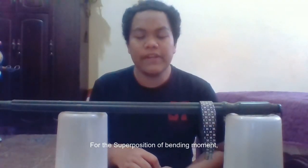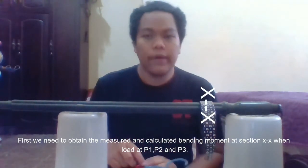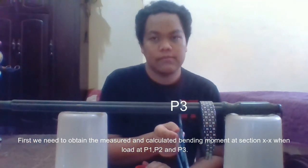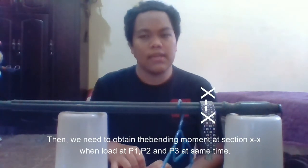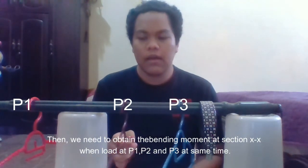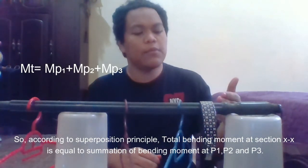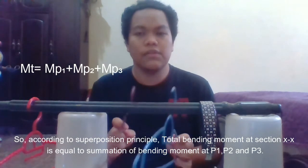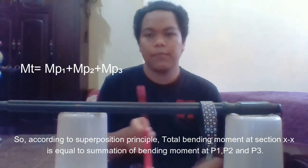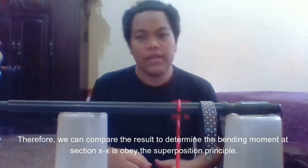For the superposition of bending moment, first we need to obtain the measured and calculated bending moment at section XX when the load is at point 1, point 2 and point 3. Then we need to obtain the bending moment at section XX when the load is at point 1, point 2 and point 3 at the same time. According to superposition, the total bending moment at section XX is equal to the summation of bending moment at point 1, point 2 and point 3. Therefore, we can compare the result to determine whether the bending moment at section XX obeys the superposition principle.